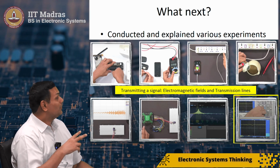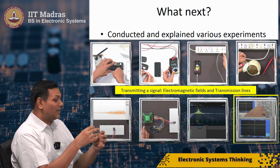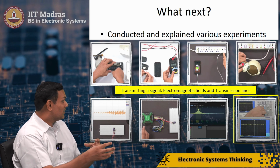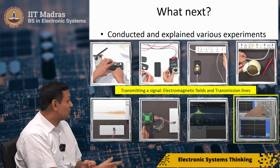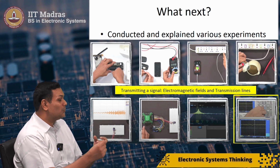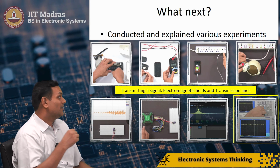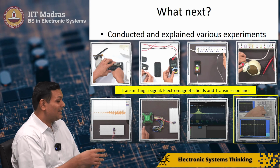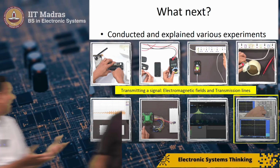Now you can go to the next level, which is imagining maybe one IC talking to another, maybe a microprocessor talking to memory. That would also technically be a transmission line because the distance would be a millimeter to tens of millimeters between ICs. There are a lot of cases in electronic systems, analog or digital, where you would have this effect.